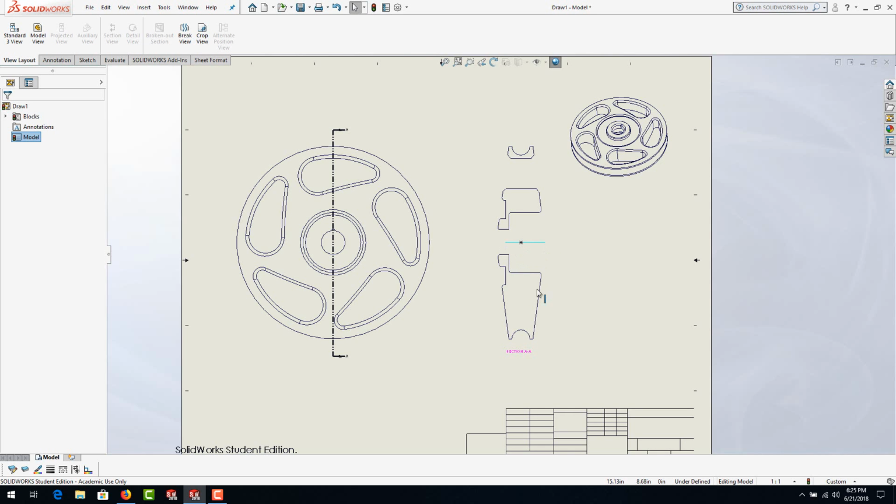We're better off taking one of these section views and bringing it in and revolving it. And in fact, we have that as our center line we could use, and it looks like this would be the most significant profile. If you look at the top profile, you have a segment taken out of it. Thus, if you revolve that, you would have two cylindrical parts that were separate. So you don't want that one.